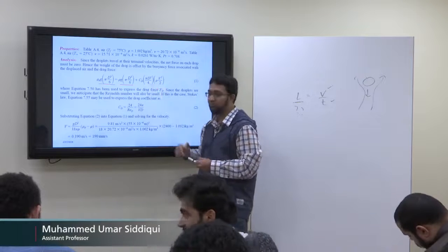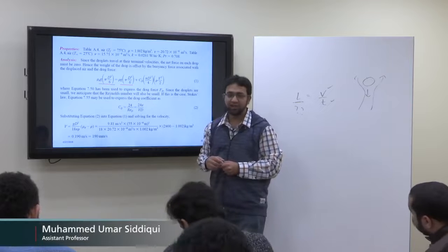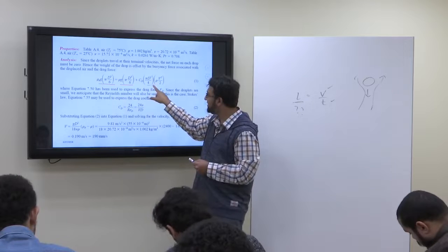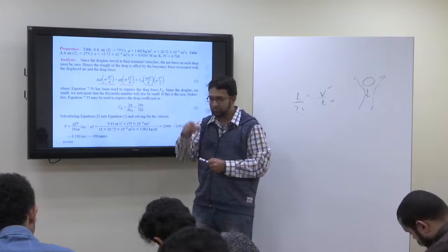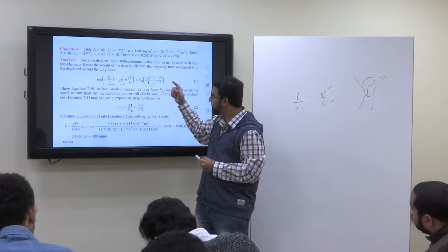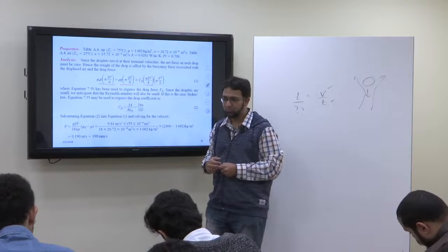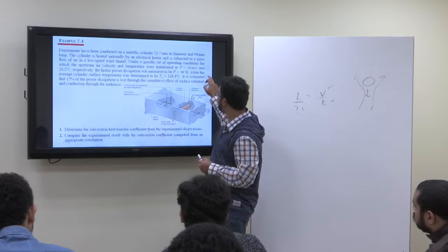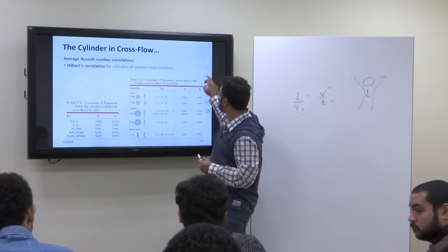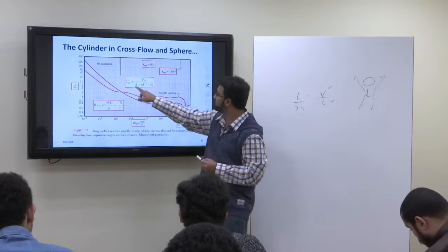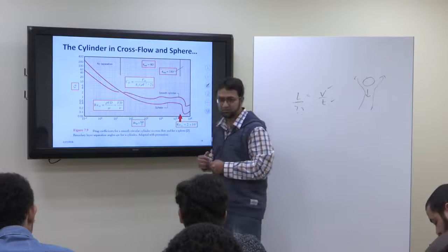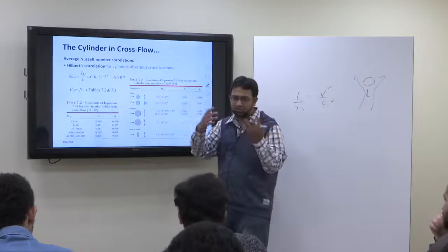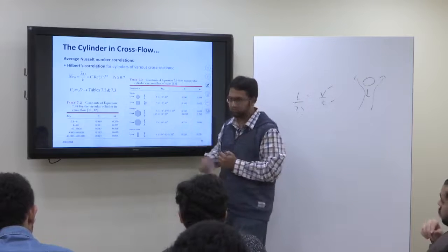And plus force of the drag. So drag force is CD times frontal area, which will be the area of the circle, multiplied by rho v squared upon 2. Remember this formula? This comes from the coefficient of drag. So two forces are acting upward, one force acting downward, and at the terminal velocity, they cancel each other.